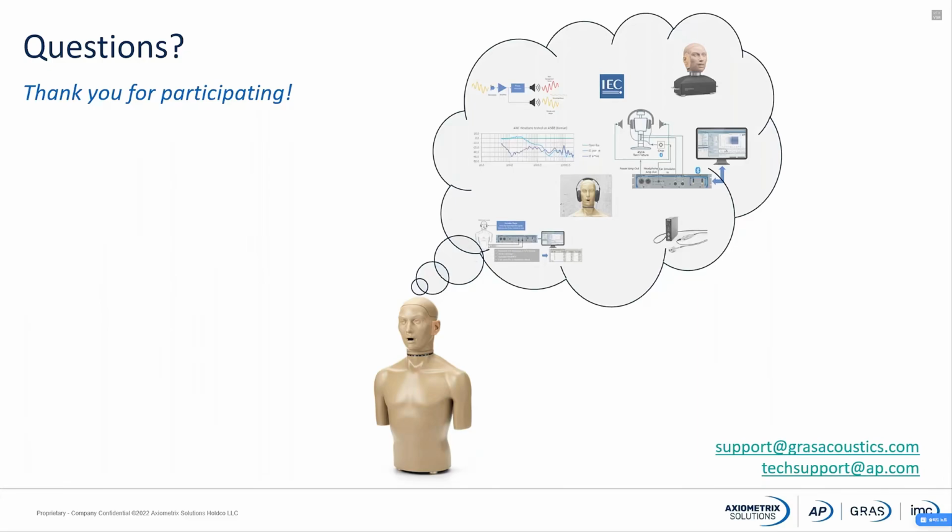Right now, if you want to measure up to 20 kilohertz, for example, we do offer our high frequency ear simulators that are still complying with the IEC 60318-4 standard, the 711 coupler standard. So if you want to reliably measure up to 20 kilohertz, we can recommend to use these ear simulators.